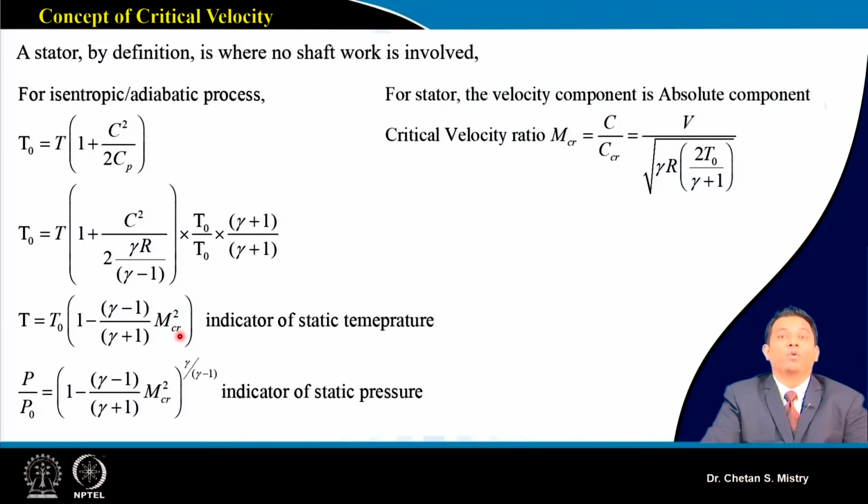In the same way, local or static pressure and total pressure, all these parameters we will calculate based on the critical Mach number. Do not get confused, and do not use the isentropic relations for the calculation of Mach number. Be careful, these relations are different from the relations for isentropic flow. Now we are modifying our equation in the sense of critical Mach number.